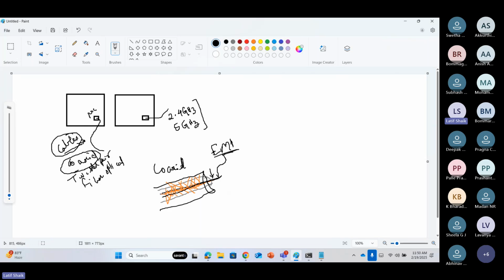Some signal is being transferred on this cable, and other different signals also interfere with your actual signal. If that happens, it is a mixture of signals, meaning your signal and other signals get mixed. That is what we call crosstalk. To avoid this kind of crosstalk, the mixture of other signals with our signal, this copper mesh is useful. It absorbs the electromagnetic interference and grounds it, so it won't let any EMI signal in.